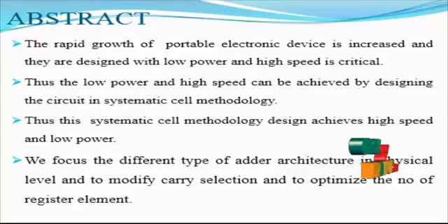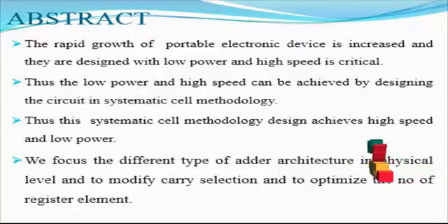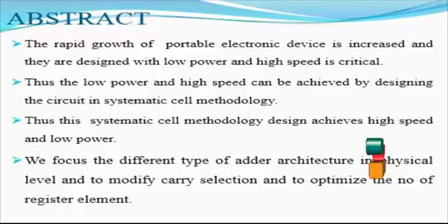Cell design methodology has been presented to design some limited functions such as 2 input XOR and XNOR and carry and inverse carry in the hybrid CMOS style. In this brief, we propose efficient 3 input XNOR circuits as the most significant blocks of the digital system, with a new systematic cell design methodology in hybrid CMOS logic style. SCDM, which is an extension of CDM, plays the essential role in designing efficient circuits.